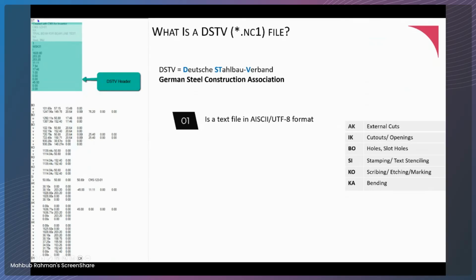Any file that you open with Notepad, you're going to see that the NC file starts with an ST command and ends with an EN command. Within the first few lines, there are some header lines, which we call header data. When it comes to Inventor, on top of those lines, in total 5 lines, we can map those lines depending on your need, or your supplier's need, or if you're doing manufacturing and fabricating on your own premises, we can always map those from your iProperties as well.